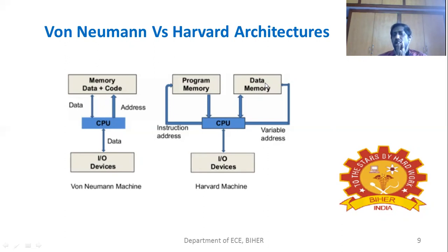What is the purpose? In the program memory, not only application software is stored. Along with the application software, we need to store the constant data also inside this program memory. For example, we are using a microcontroller based motor control system. In such systems, we can use lookup tables. The lookup table is constant data. So the constant data can also be stored in the program memory.